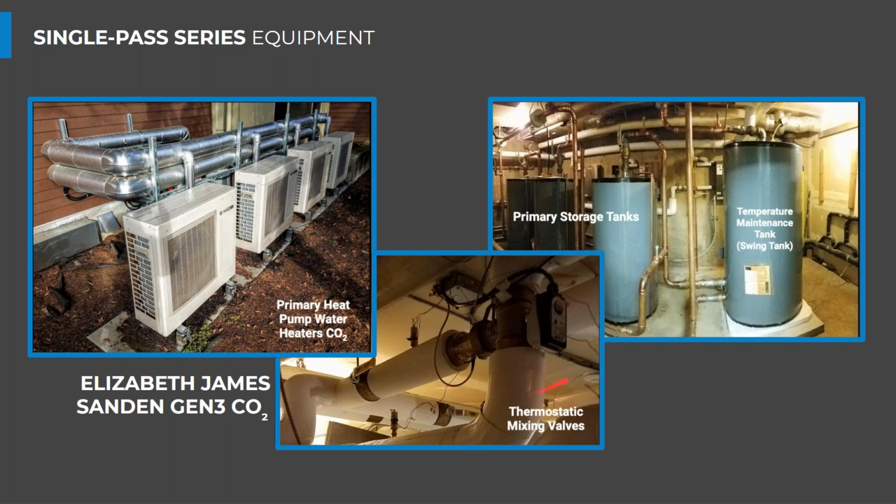Here's our thermostatic mixing valve. It's a much smaller valve. I showed a lot of larger valves for larger buildings, but these electronic mixers are also available in smaller sizes, and I would encourage the use of that type of thermostatic mixing valve, especially with swing tank systems, as the temperature on the hot side of this valve is designed to fluctuate in that system approach.